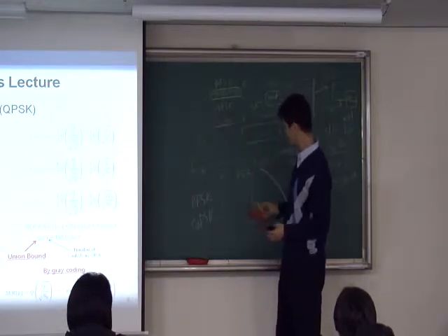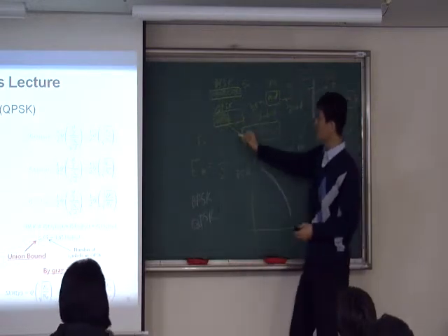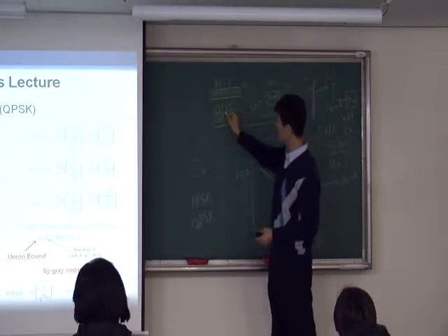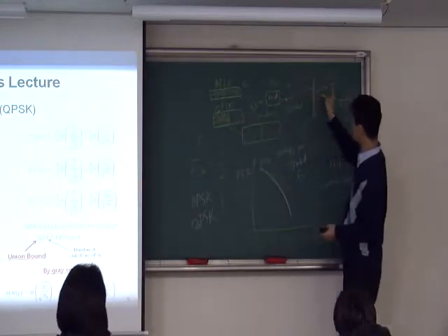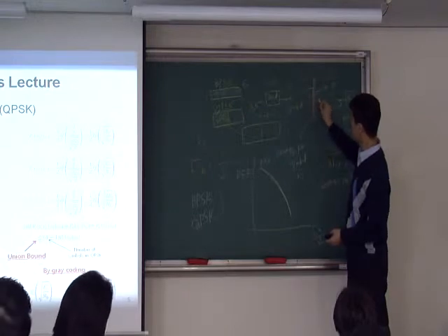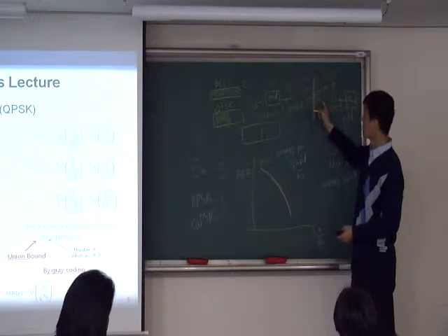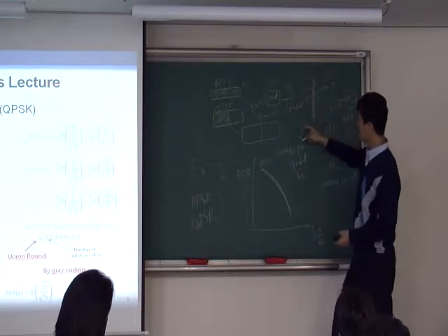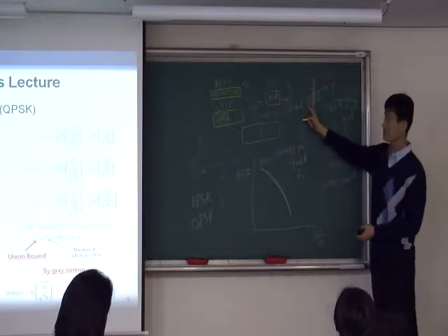So in order to make the same energy per bit, I make it a little bit bigger like this. So this area, the energy, should be the same as this energy. Therefore, if you think about the energy in the symbol, now it's double the energy in one symbol. So right here in the channel, you have a symbol flowing around. If you think about the Es at this point, the Es of the QPSK signal is double the Es of BPSK right here. Okay?